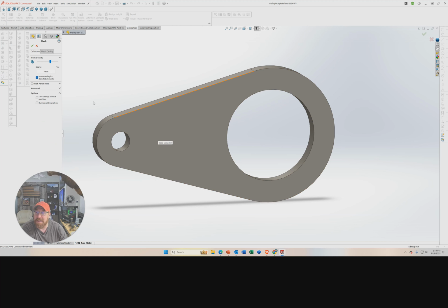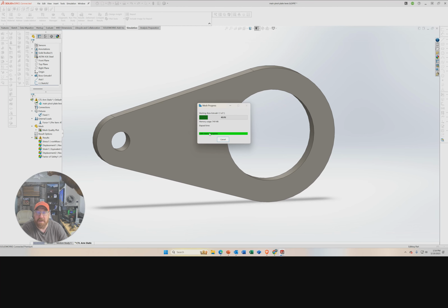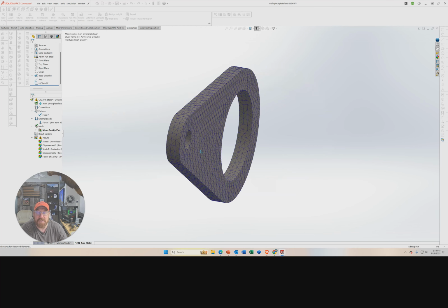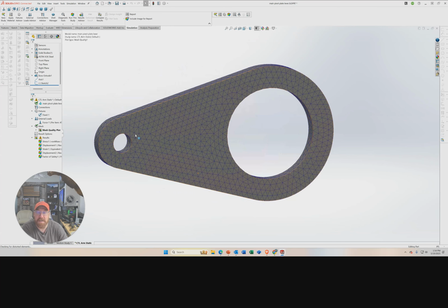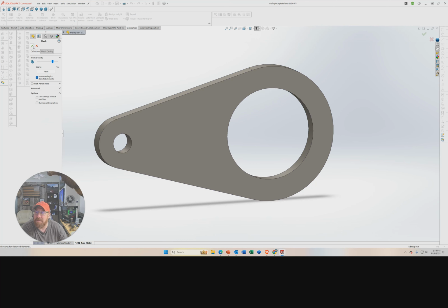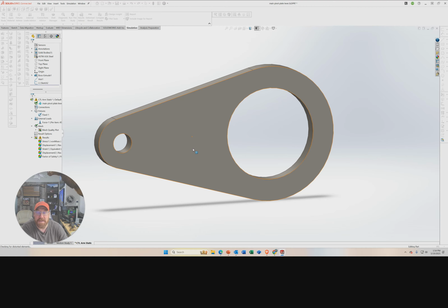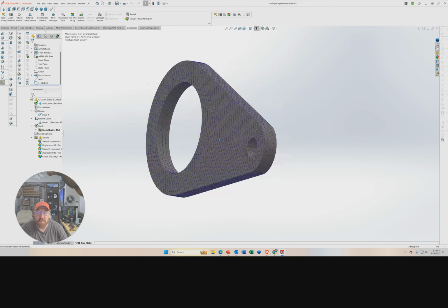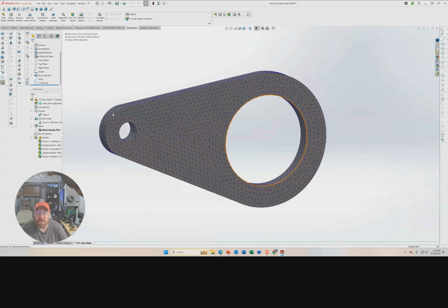It just told me that it'll delete the old study. So we tell it how fine a mesh density we want, and we hit go. What's amazing is that this actually makes that mesh on this part. As you can see, it's not a super fine mesh, but okay for our analysis. If we wanted, we could create a finer mesh. Let's go a little finer. This will get us slightly better results, but it also takes more processing power. So you have to balance that when you're doing this kind of analysis.